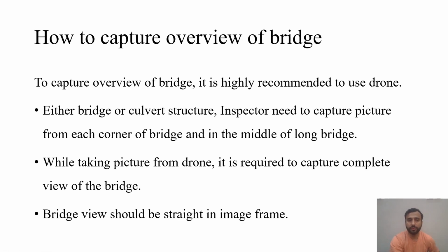So now, how to capture the overview photo of the bridges during the visual inspection. To capture the overview of bridges, it is highly recommended to use drone cameras. Either a bridge or covered structure inspector needs to capture images from each corner of the bridge and in the middle of long bridges. While taking pictures from a drone, it is required to capture a complete view of the bridge.